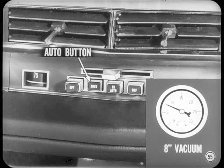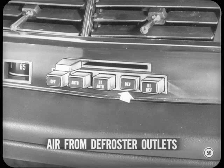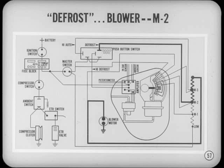So push the auto button and set the tester vacuum dial so the gauge reads 8 inches. Pushing the defrost button doesn't change the vacuum reading, but the air conditioning outlets will be closed off. All of the air will be coming out of the defroster outlets except for the normal 20% bleed through the heater doors. The output air temperature will be the same as in the auto position, but the blower speed will be in M2. That's because the current from the push button goes through only 2 resistors in the resistor block.